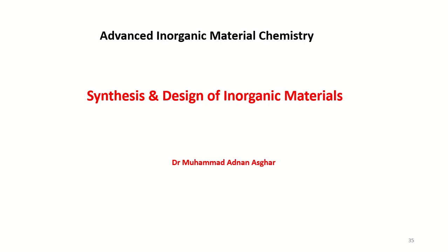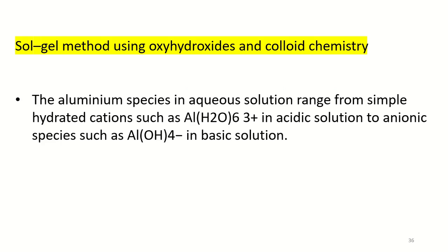Now I would like to discuss the sol gel method, which actually uses oxyhydroxides and colloidal chemistry. Sols and gels can be made from inorganic oxides and hydroxides by adjusting pH to form polymeric multi-cation oxyhydroxyl species at intermediate pH values.